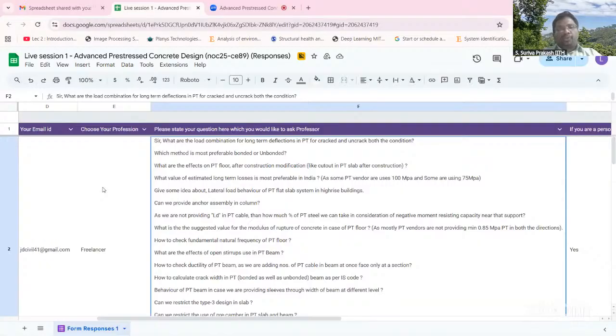we have to ensure that, particularly nowadays, people are going for precast kind of system, right? So when you have a precast kind of system, the screed has to be designed really well so that it is going to connect everything together. And similarly, we need to ensure that the reinforcement from the floor slab is also tied very well to the lateral load resisting system. So basically, you have to ensure a very good diaphragm action, right? So that is a critical thing here.